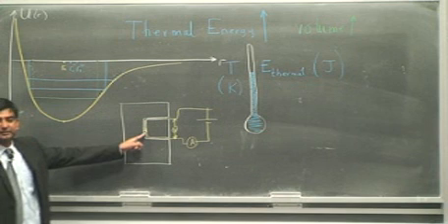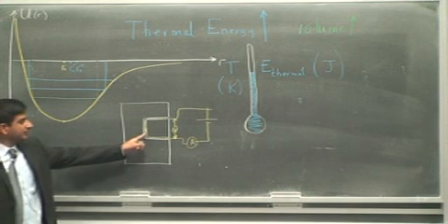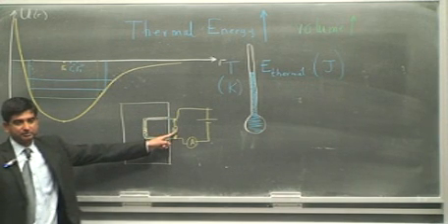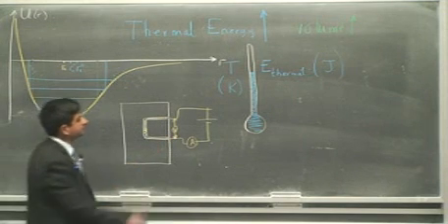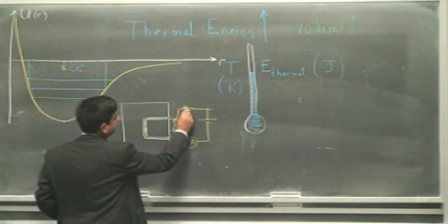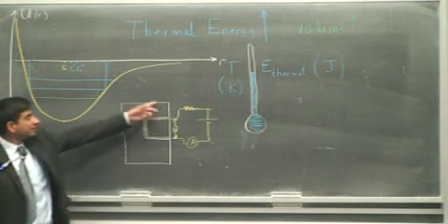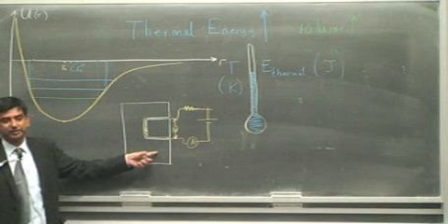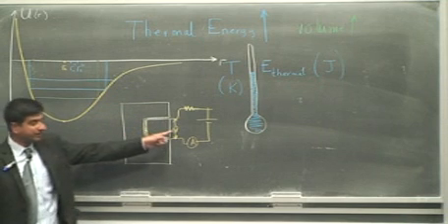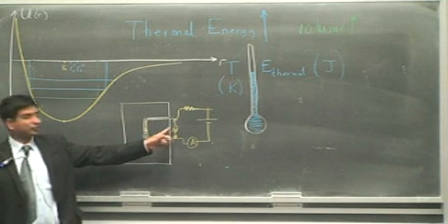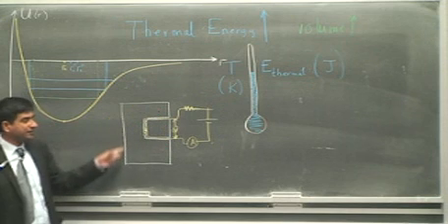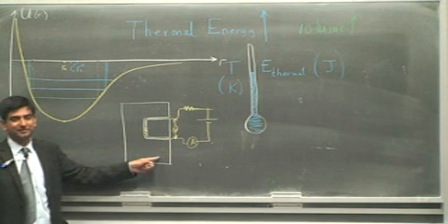So depending upon the resistance of this resistor, the voltage will change. Suppose I have another resistor in series as well. So this resistance will change with the thermal energy of the atoms inside the solid, and this resistance change will be registered as a change in voltage. So this voltage is a measure of the thermal energy inside the solid,